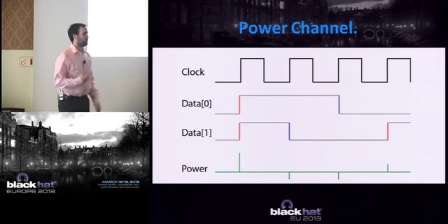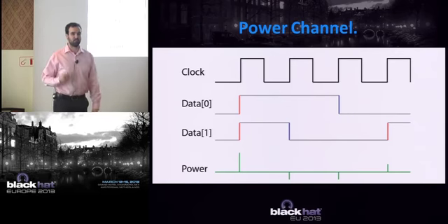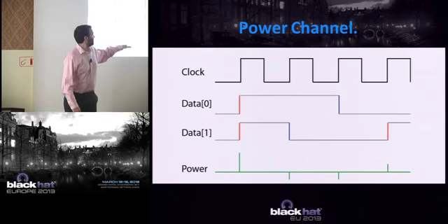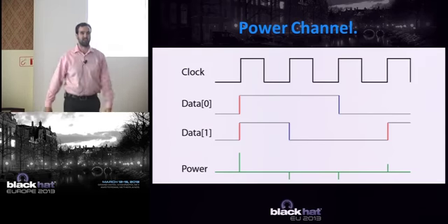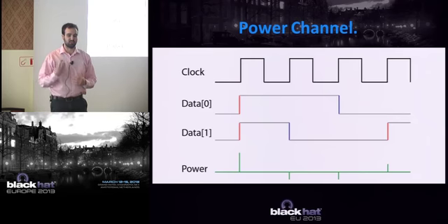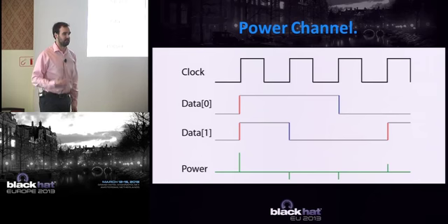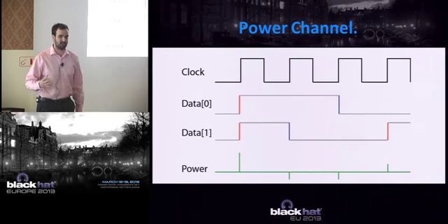Where this comes from is the buses do something called a precharge. You can imagine if the data bus switches from all ones to all zeros, this would be the worst case power consumption. This would require the most charge. Your worst case is going to limit your device in terms of speed and things like that, how fast they can go over the data bus.